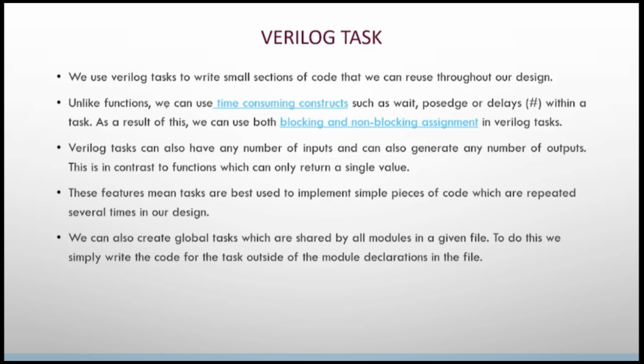Now coming to task, as we already discussed, when you want to use any delays or any passage of clocks, and when we can use both blocking and non-blocking statements, mostly when you are using any time consuming constructs, you can go for a task instead of functions. And as I told you, a Verilog task can have any number of inputs, and it can generate any number of outputs also.